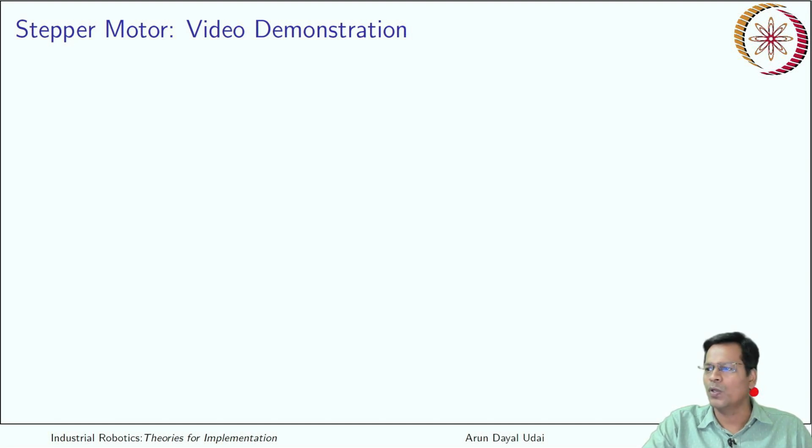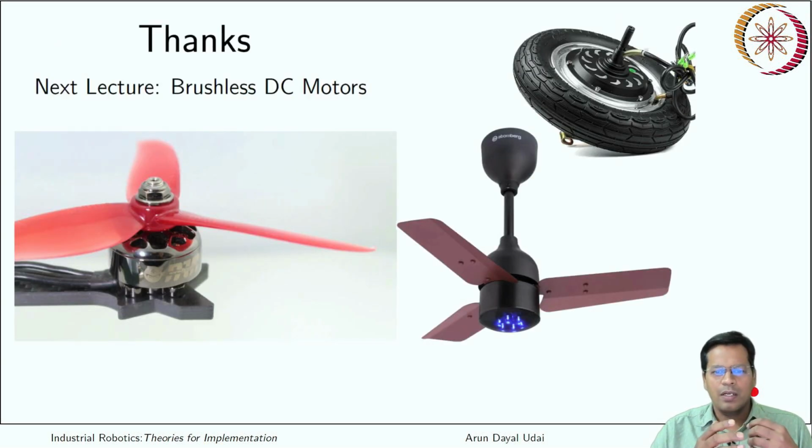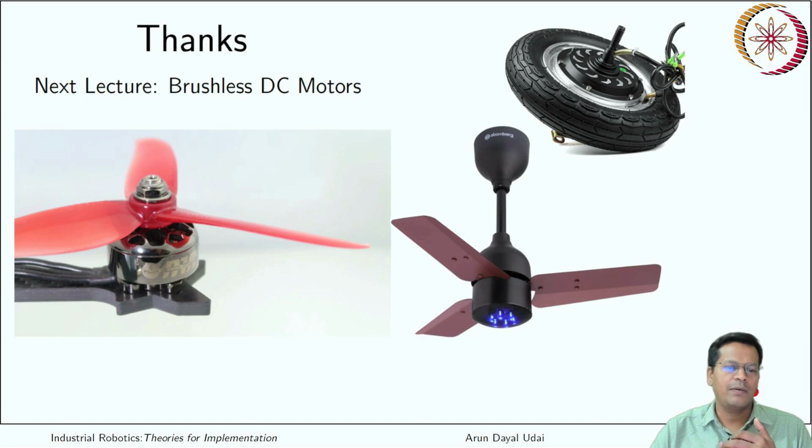Now you know very well how a stepper motor can be made to run, the different types of stepper motors, how they are internally connected and how they are constructed. Not much in detail for micro stepping have you learnt, but you at least got the philosophy here that it is very much like a bipolar stepper motor, and you can gradually shift the pole using a current chopper drive. That's all for this class. In the next class, we'll be discussing more about the brushless DC motor. That's all. Thanks a lot.